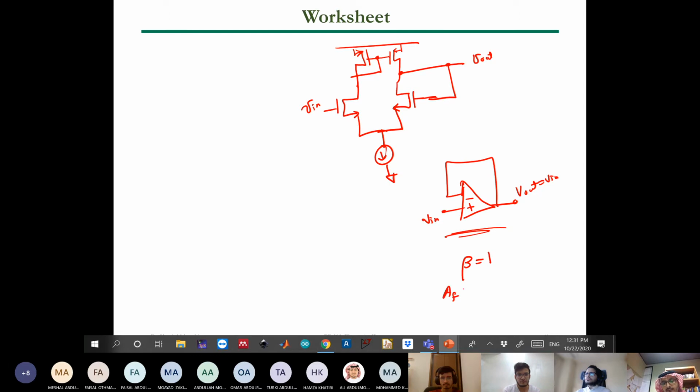So what is the gain? It is A multiplied by 1, divided by 1 plus A. And of course, A usually is high. The open loop gain of the op-amp usually is a few thousand. So this one will be almost 1. Do we have a feedback or not? The gain has a reduction, right? It is almost equal to 1. So this is still a feedback. And what is beta? Beta here equals 1.